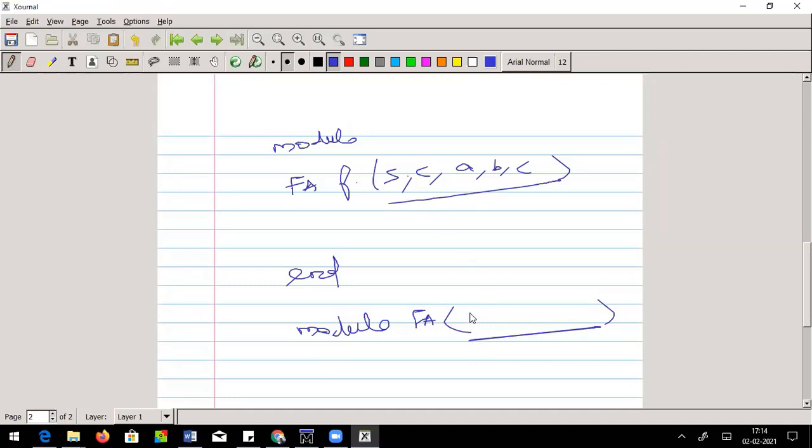So whatever name you have given, like sum, carry, it could be any name: sum, su, ca, a1, b1, and c in. But the point is, the order of the signals which you have given in this full adder definition should be followed in this.